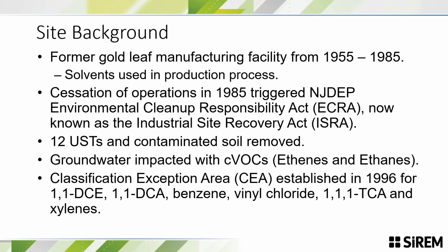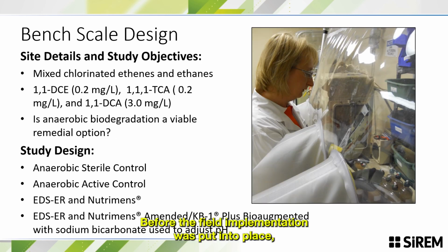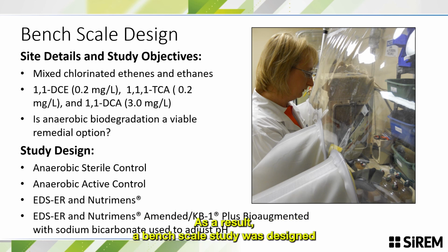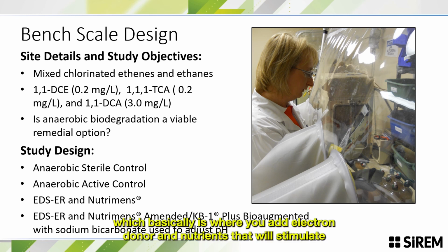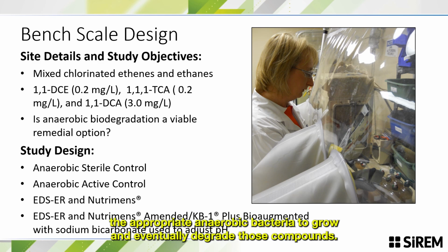2015. Before the field implementation was put into place, the operating consultant wanted to confirm that anaerobic biodegradation was going to be a viable remediation for this site. As a result, a bench scale study was designed, looking at degradation of mixed chlorinated ethenes and ethanes using an anaerobic sterile control, anaerobic active control, a biostimulation treatment, which basically is where you add electron donor and nutrients that will stimulate the appropriate anaerobic bacteria to grow and eventually degrade those compounds.